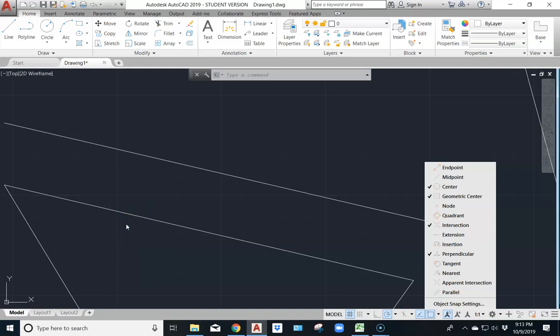However, if you add a z-axis, which is coming towards you to create depth, that gives you 3 dimensions, and it sometimes happens that while from one view it looks like two lines cross over each other horizontally and vertically, if you then rotate them on the z-axis, you might see that there's a height gap in between them. However, this tool allows you to snap to that apparent intersection where they would meet. We don't use it typically in this class because we're doing 2D AutoCAD. And finally, you can snap to a line that you want to create parallel to another point.